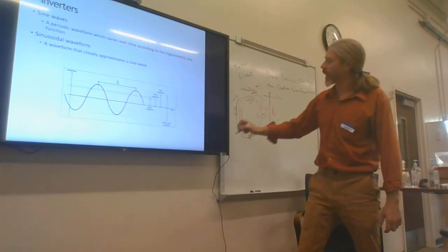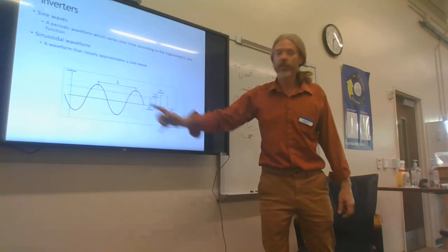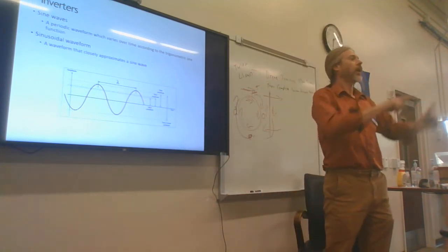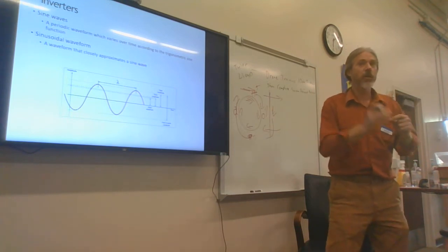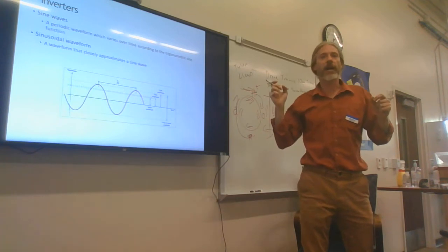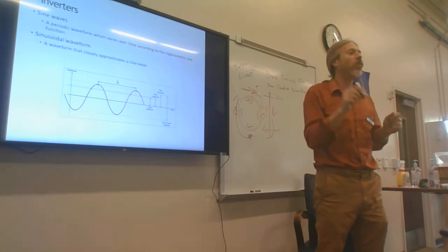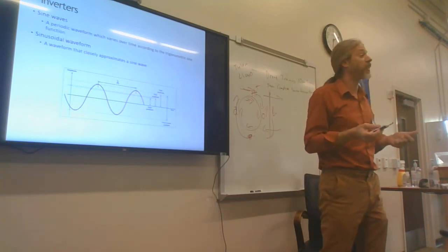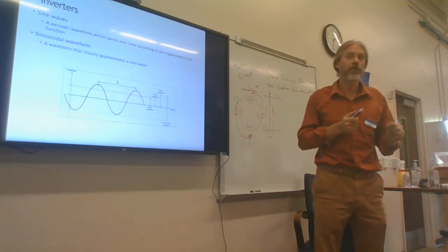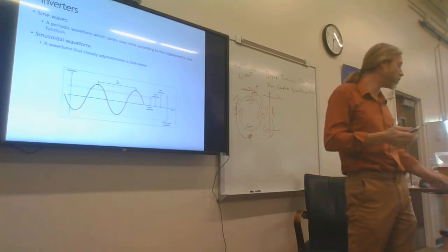Then I return to my parallel angle. I've made one complete rotational cycle, going from 0 to peak voltage to 0 to peak negative voltage and back to 0. This shape was created because we created electricity through rotational generation. That's why we use the sine wave.